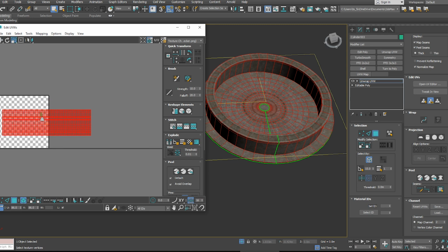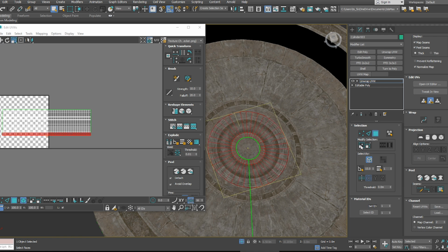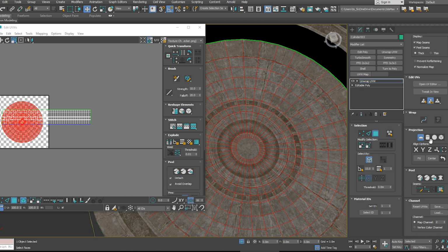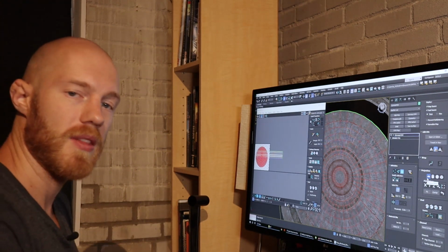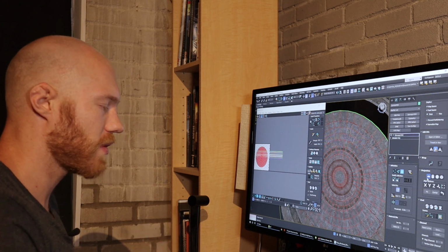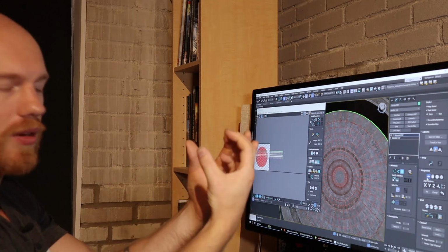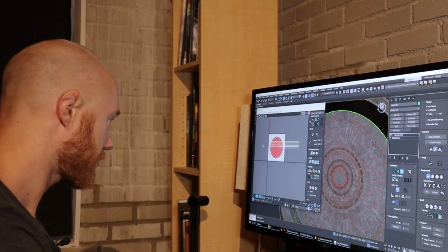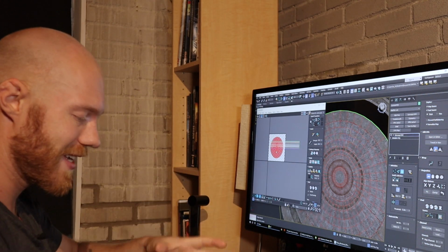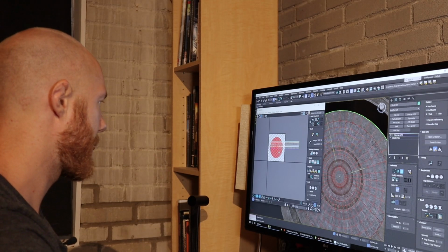But what I'm going to do is, now that that's done, I'm going to just quickly select this face, grow the selection, give all these faces a planar again, because I want that to be a proper non-stretched shape. Just because when you bake your lighting, the light map UVs are basically getting a render to texture of the lighting information, so I don't want it to be rendering a round flat surface and stretching all that lighting in a weird way, if that makes sense. I just want it to be able to render to texture a nice clean version of all those faces.